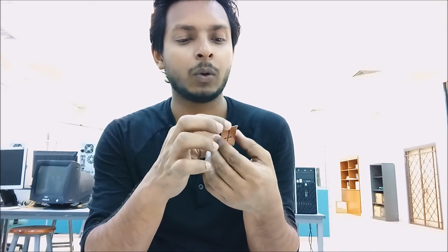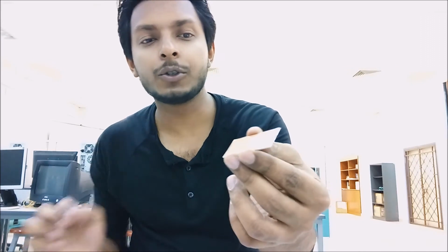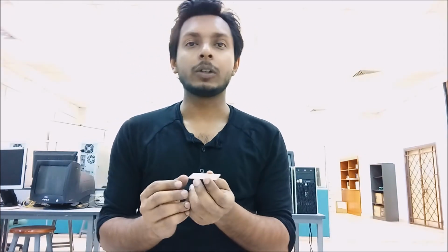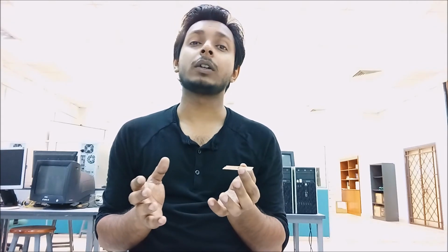One point is very important while you're protecting the ground plane with this duct tape: make sure there is no bubble, especially on the outer area of this surface, just like the edges. You must have no bubbles, because they can damage your ground plane by letting the chemical materials reach it. So now we will make a solution. That's the basic thing, the main part of the etching process.